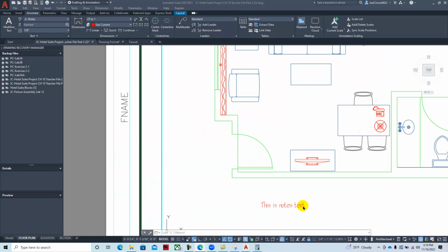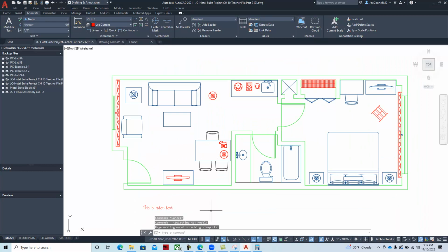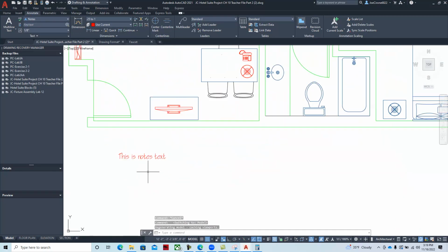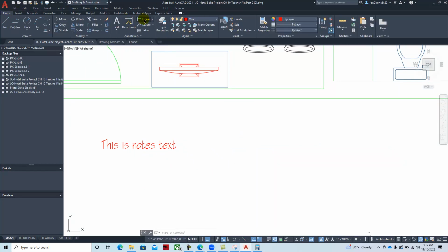If we take a look at it, text height looks great. We're working within what they call floating model space, which is within that viewport. That's why we see the UCS icon. If I come in here to model space, here we are, this is our text, and I'm not sure if I can throw a measurement on it, but if I can kind of just guesstimate it, see, it's almost 6 inches tall, and I'm just guesstimating it. So yeah, it's working really quite well. It's doing what they're saying it's doing, even though my math might not be perfect.